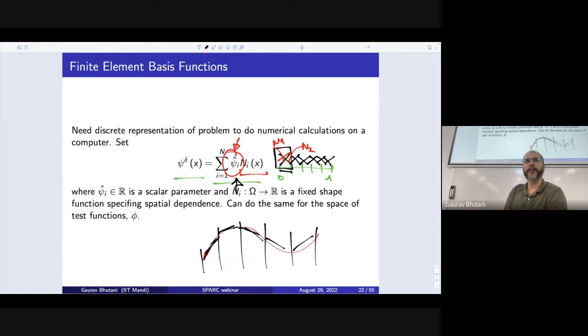That's a very important idea in the finite element method, that we choose a set of basis functions coming from a space. Linear space is very comfortable for us, and we say that we can fit any function using linear functions by simply changing psi hats. So our problem now simply boils down to finding psi hats, and of course I have to substitute this into the main equation and then find psi hats based on the given equation.